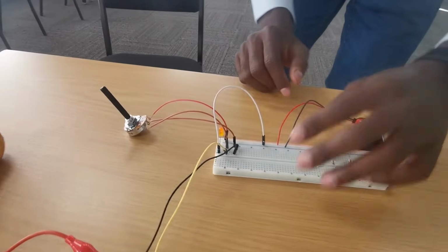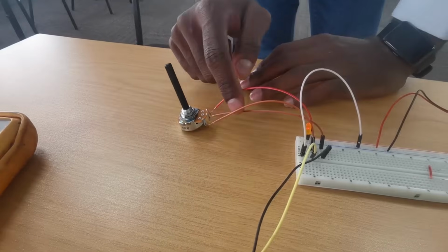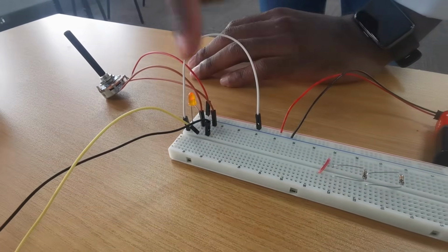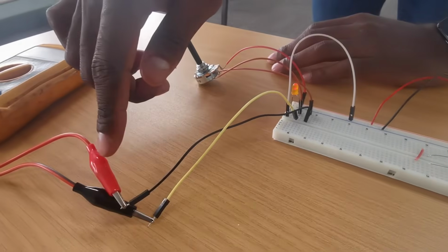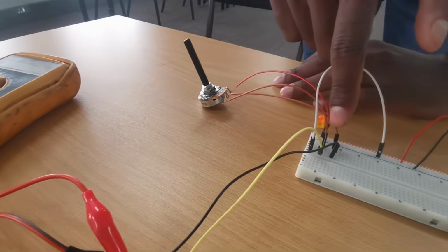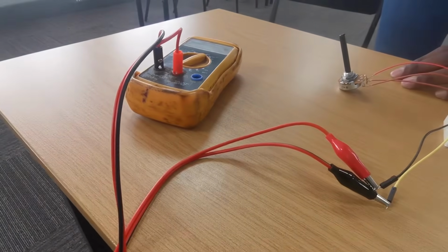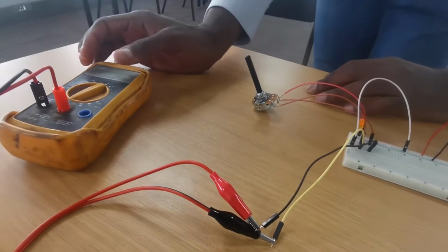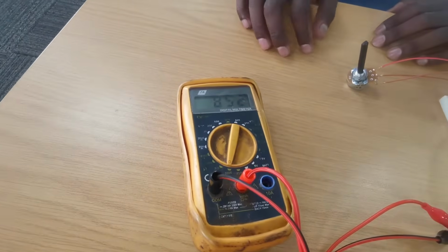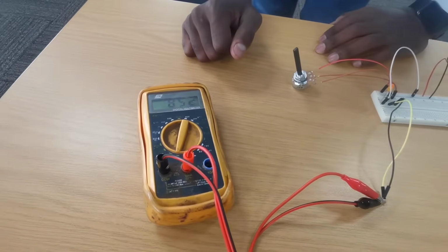And essentially what you then need to do is the positive and the negative leg. So that positive leg you see there, I've connected it to the positive of my multimeter, and then the negative leg, which you can see there, I've connected to the negative of my multimeter. And I change my multimeter to ohms, right? That's how now you'll measure the resistance. You can also do this for the normal resistors when you want to measure the ohm value of the resistor.